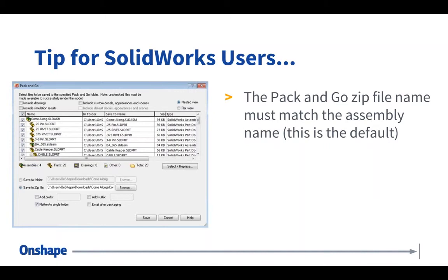Okay. Question, import pictures to a drawing. You can import pictures into a sketch in your Part Studio. You cannot import into a 2D production drawing, but if you're trying to import a picture into a sketch, you can do that today. You'd import the picture and use the sketch image command while in a sketch to insert it. Forgive me if that's not what you're asking.